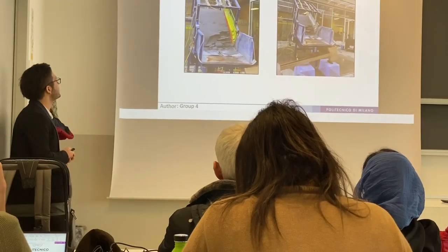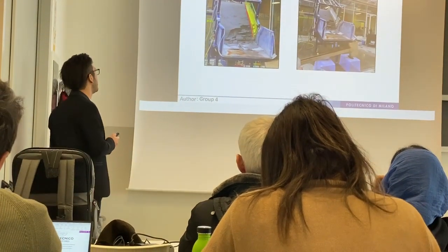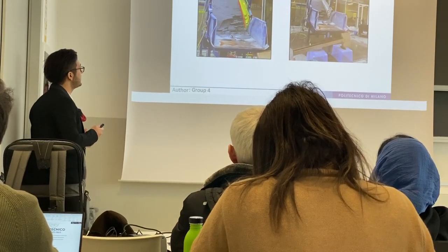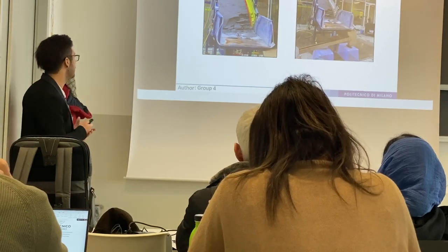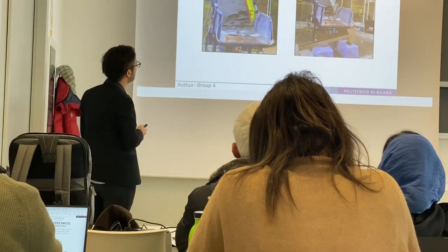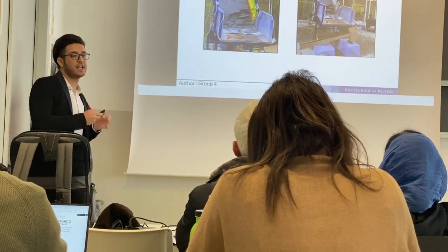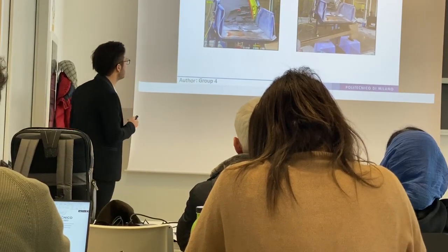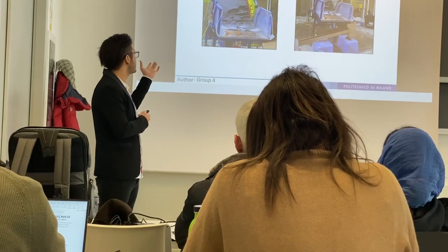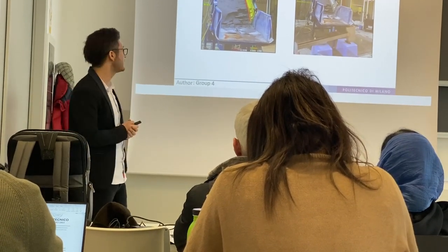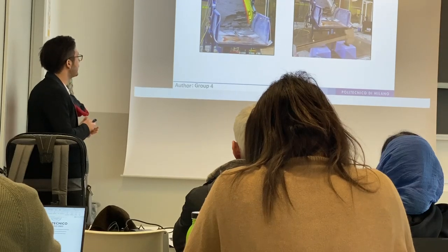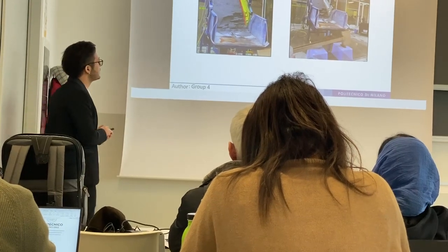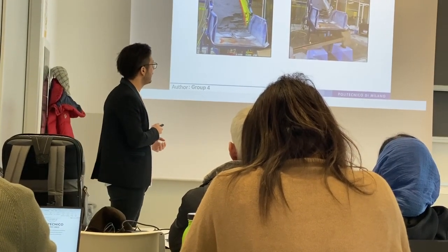And also, there are some suggestions for doing a better experiment. One of them is the boundary condition problem. Some amount of rainfall hits this wall, the highlighted yellow wall here, and that goes into these boundaries. So if we can change the way of the rainfall and collect it, we can remove this problem. And this was seen in every single experiment. The failure started happening either on the left or on the right side. So this was due to the boundary condition problem.